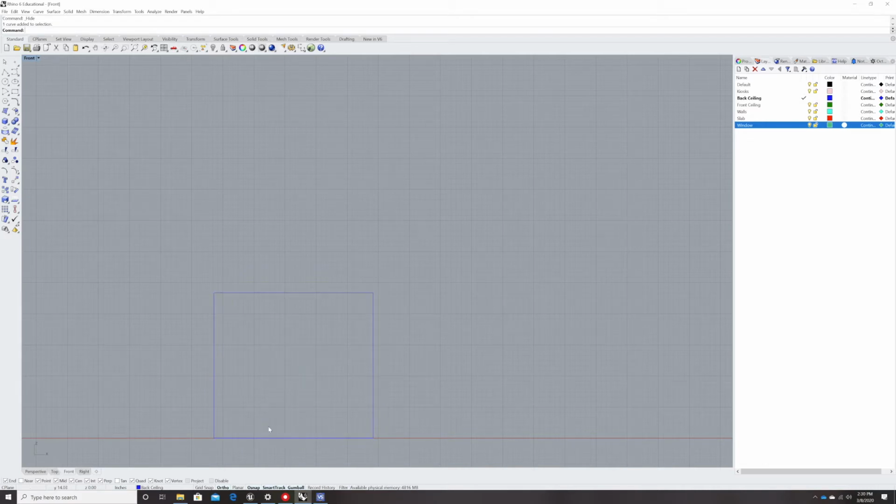So I'm going to do an 8-foot by 8-foot opening for the window here. That will be for the two doors. And then I'm going to do the windows around. Okay, so 8-foot by 8-foot. So I'll draw a rectangle, come from the center line here, and start to draw. And I'm going to do 4-foot, enter, 8-foot, enter. And then copy from this point to this point, enter. Those are our doors.